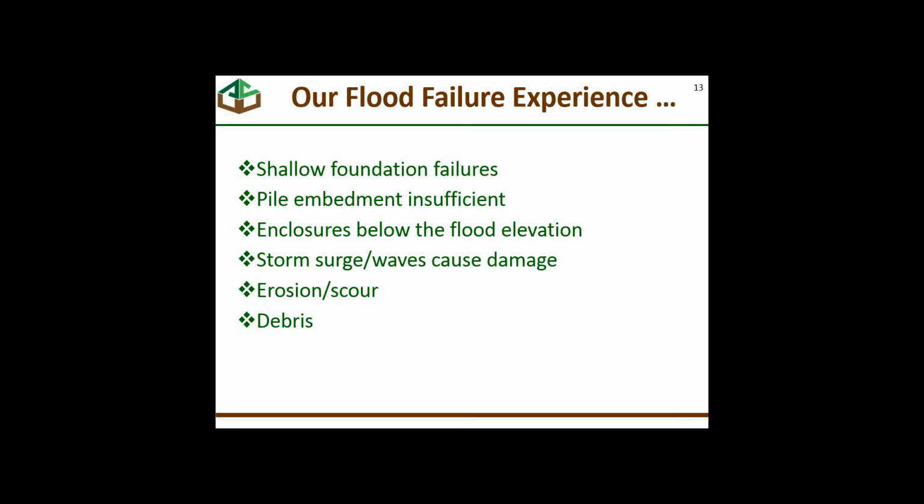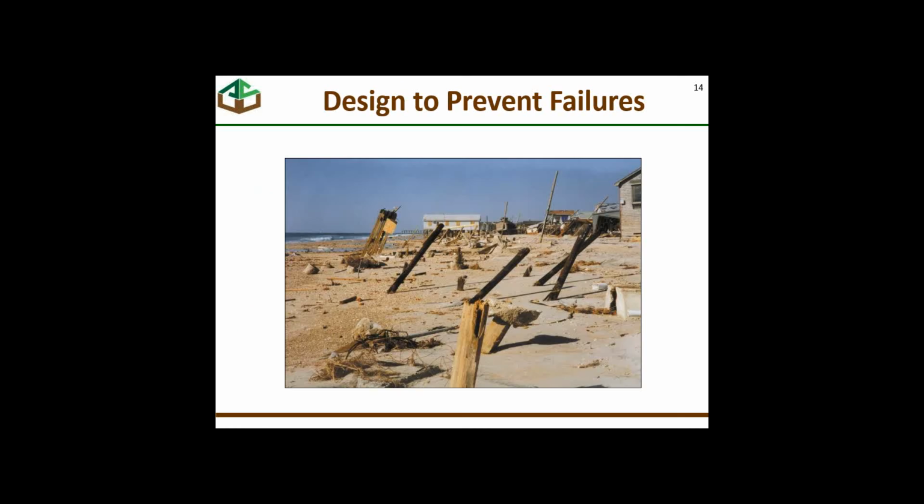The designs that I have done, I have typically tried to design to prevent failures. So in most cases, I try to get loads to the LRFD level, the ultimate stress level, because I frankly, at least for what I've seen happen in the field, I care a lot less about just overstressing a pile, having exterior fibers stretched in a pile. I care that this doesn't happen. So what we're trying to avoid is a pile snapping off like you see here.